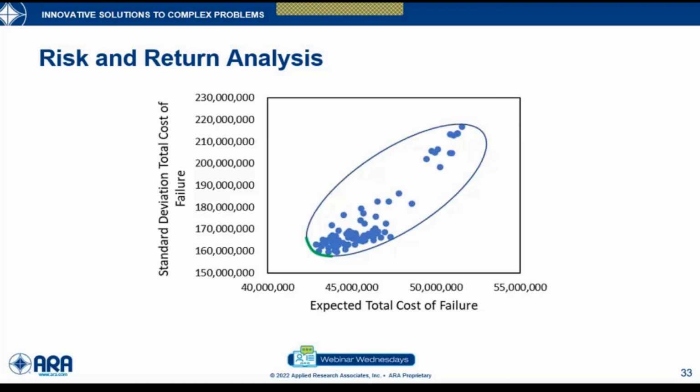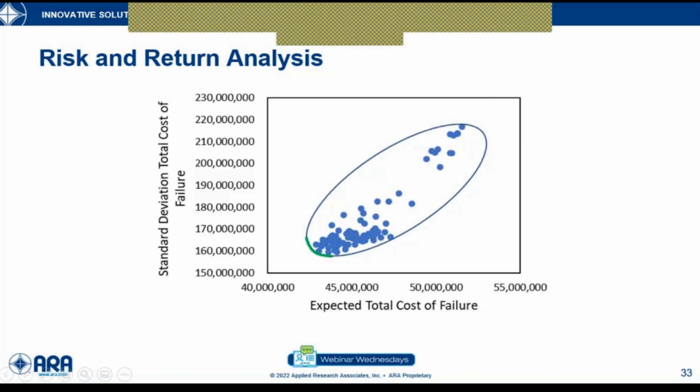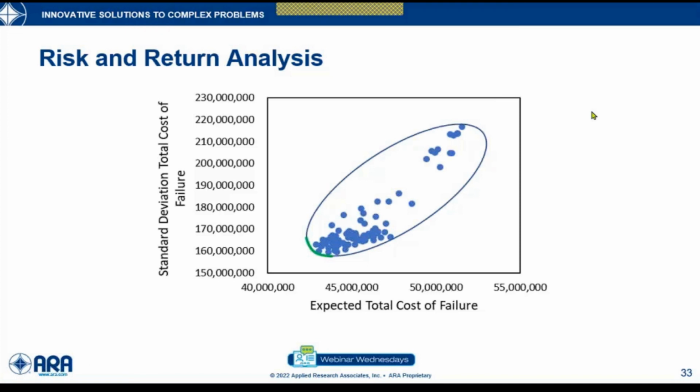Because in many cases, non-destructive evaluation does not always give direct engineering measurements. It could give you an indication, for example, of a zone that collects water in the back of the wall, for example. And that would basically help in going back and assessing that specific slope or wall and so on. So that would be one of the approaches to incorporate non-destructive evaluation.